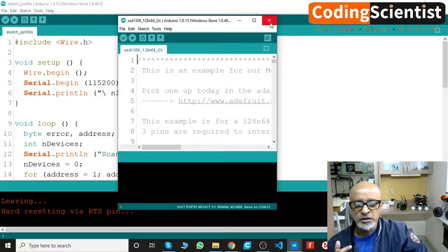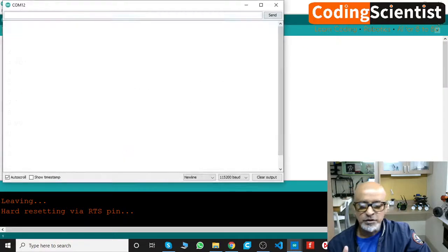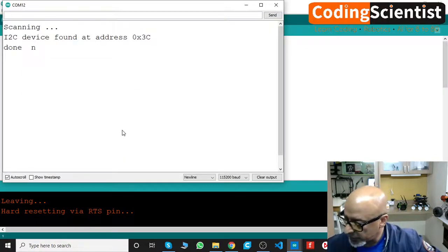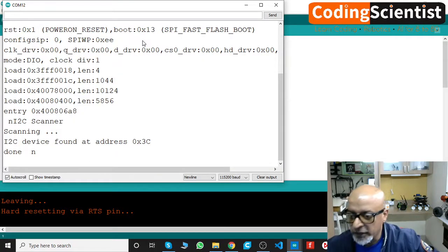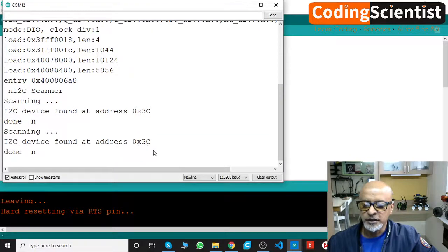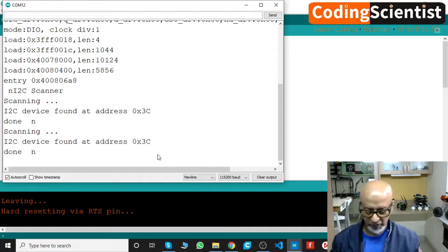Now, let's read through which was the bus we connected. I just forgot. Oh my god, it's very important to write it down. Okay, device found at I2C. Let me just reboot. Let me click the EN button again. I clicked it. 0x3C. Let me just make a note of it because I forget it, guys.